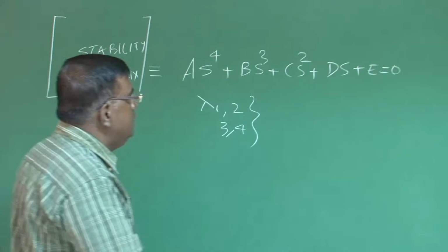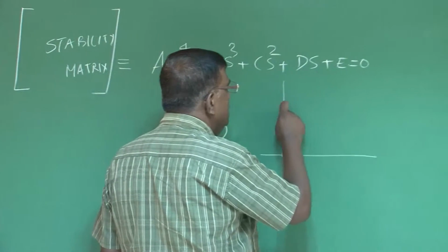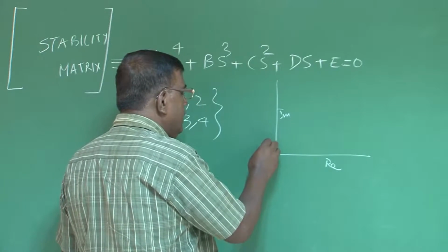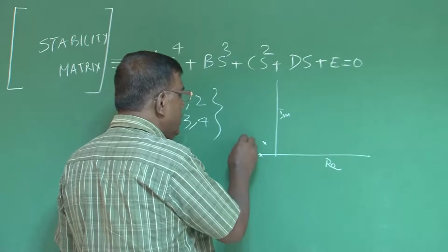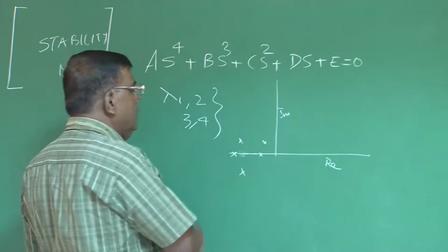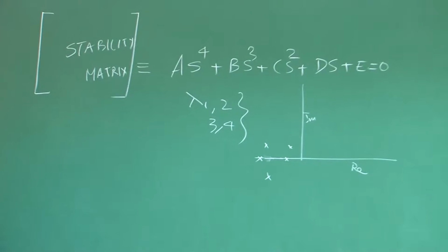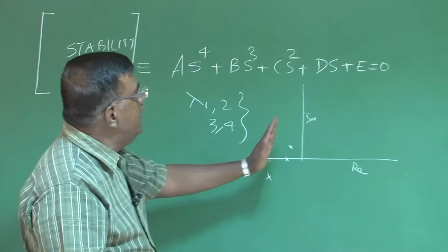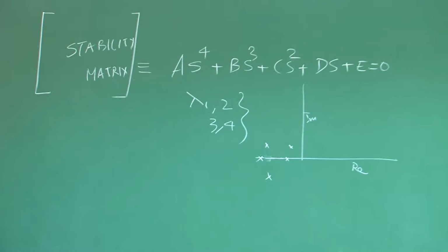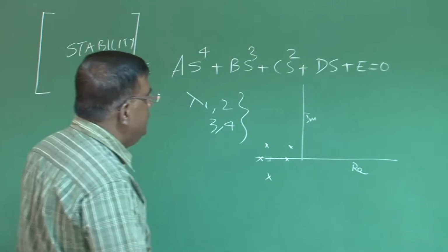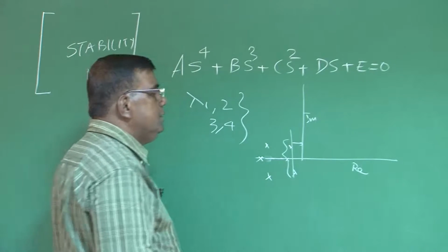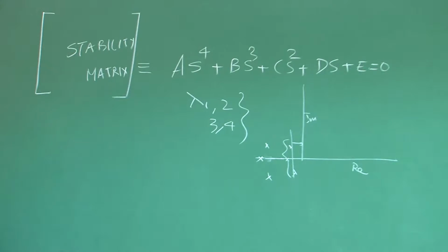And we also realize that if we plot the imaginary and real part of the root, we wanted them either this way or maybe on the real negative side. What was important is that the roots should lie on the left half plane to ensure that there is convergence. But the question comes, how far from the real axis, and what is the magnitude of this if it is a complex conjugate? That depends upon what?